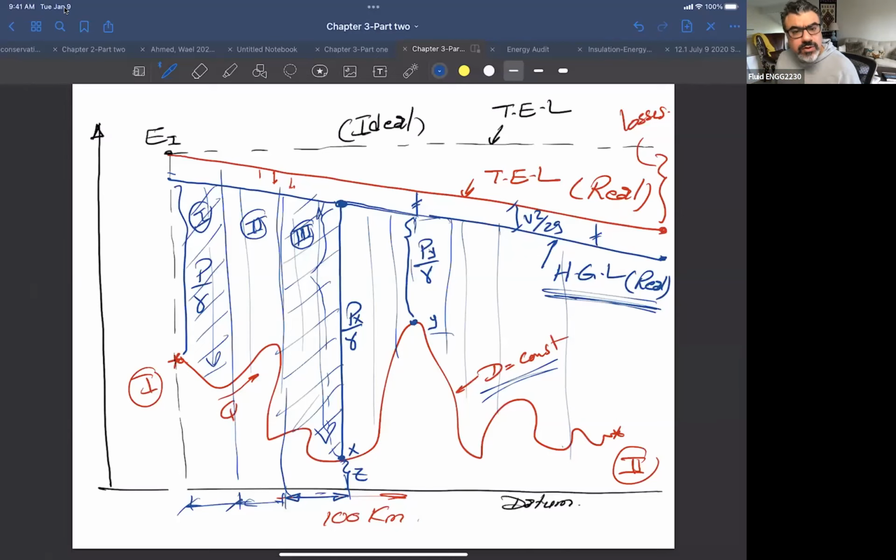So then you decide what kind of thickness. When I'm talking about a pipeline that is extending for hundreds of kilometers, the most important type of cost here is the material itself. We're talking about, let's say, a 48-inch pipeline or something like that, or 30, 36-inch pipeline.